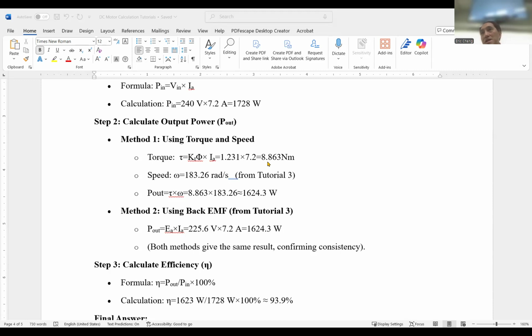And then we may have a feedback loop in order to continuously maintain this high current for a short period of time during the startup. So you can see here, the average voltage is 80 volt, but the armature current IA is 250 amp during the startup.